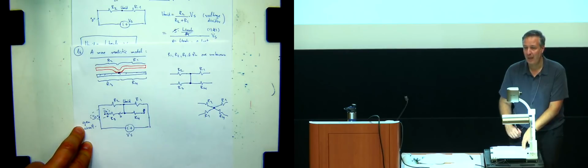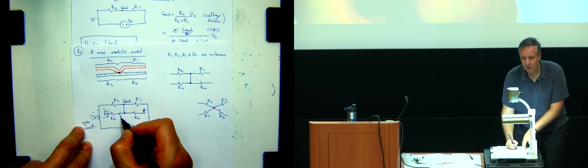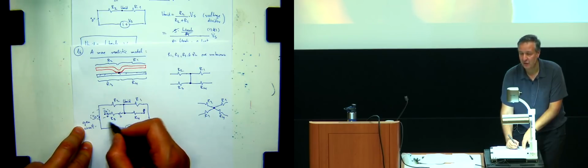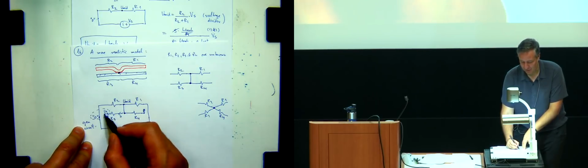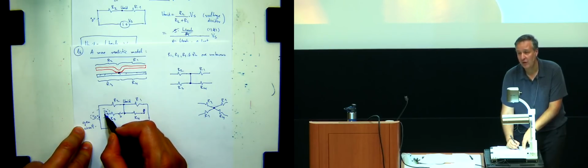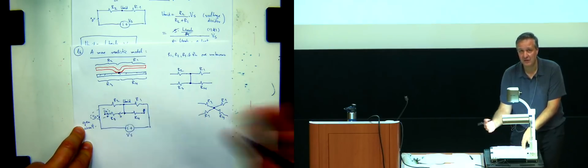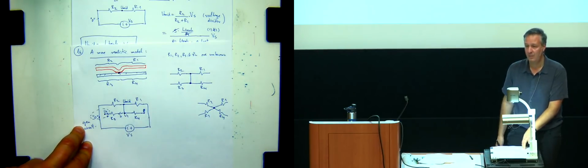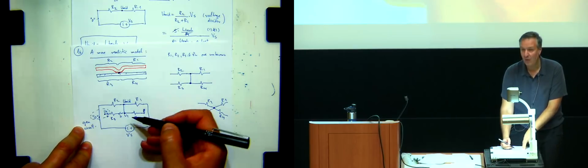And then use Ohm's law and determine voltage across R3 is 0. Yeah, so then Ohm's law says if the current through the element is 0, and that element is a resistor, then the voltage across the element is 0. So that means that the voltage between these two points is 0. Well, if the voltage is 0 and voltage is a difference in potentials, that means that this thing is also U1. Okay? And now, the last step.